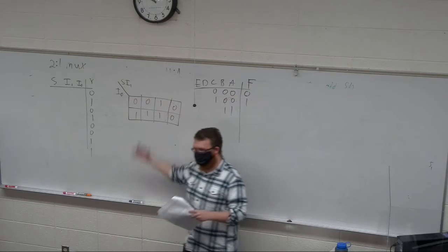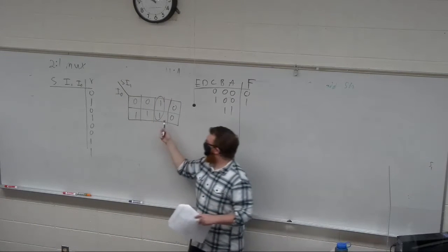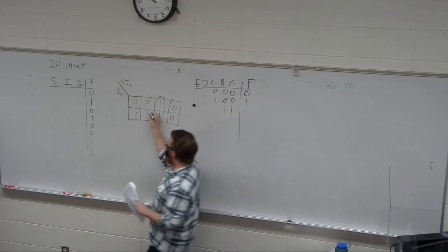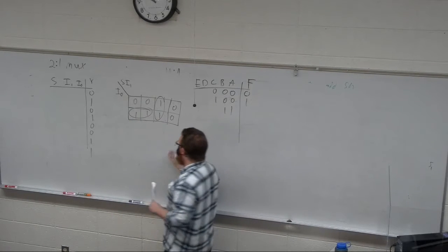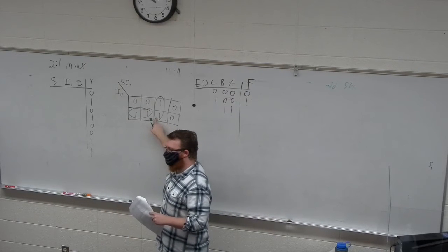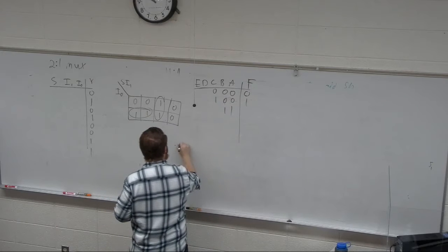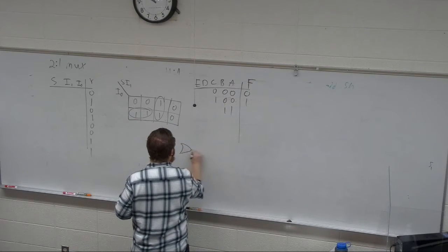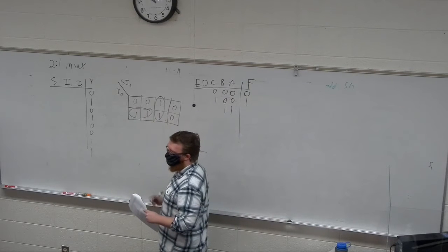Okay, I have that K-map. One good implicant, 2 good implicants. Now, the output of this one, when I'm using ones, right, is sum of products. So that means my output gate is an OR, and I have 2 AND gates with 2 terms each.